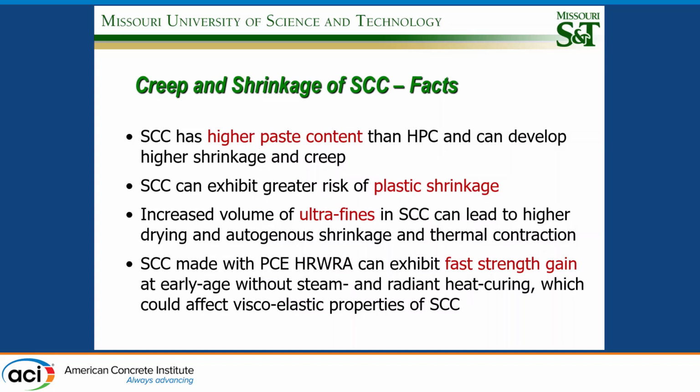All of these tell us that, yes, if you don't modify your mixture, it's going to have more shrinkage, more creep, and also a lower elastic modulus. When we use superplasticizers, such as the polycarboxylate ethers targeted for precast, prestressed applications, we want very high early strengths. And that also can bring on some issues with autogenous shrinkage at early age and later behavior.